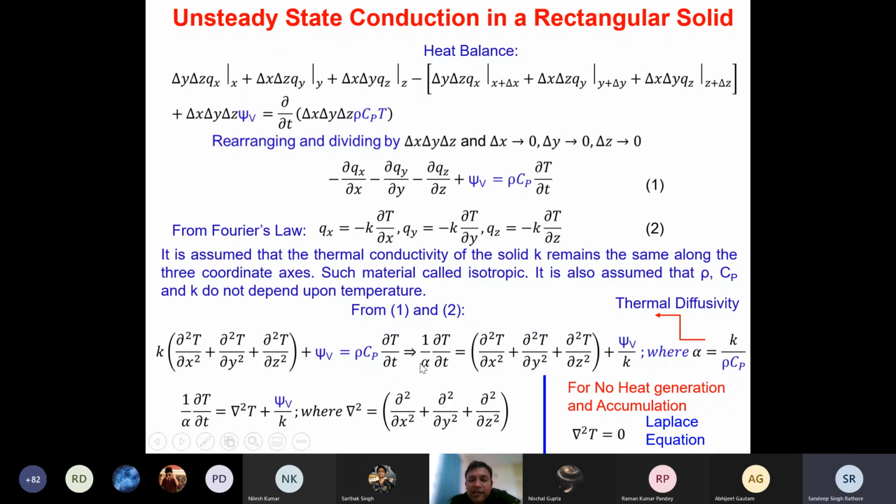Now what I'm saying is this time and this x are very important parameters, because very often you look at systems where some of these become limiting. That means you get an infinite or semi-infinite type of geometry. A typical example is Couette flow. When your velocity is going to become the same as a flat v naught, that particular length depends on several parameters, but very often you represent that length using some other parameters, isn't it? Instead of taking it as an infinite length.